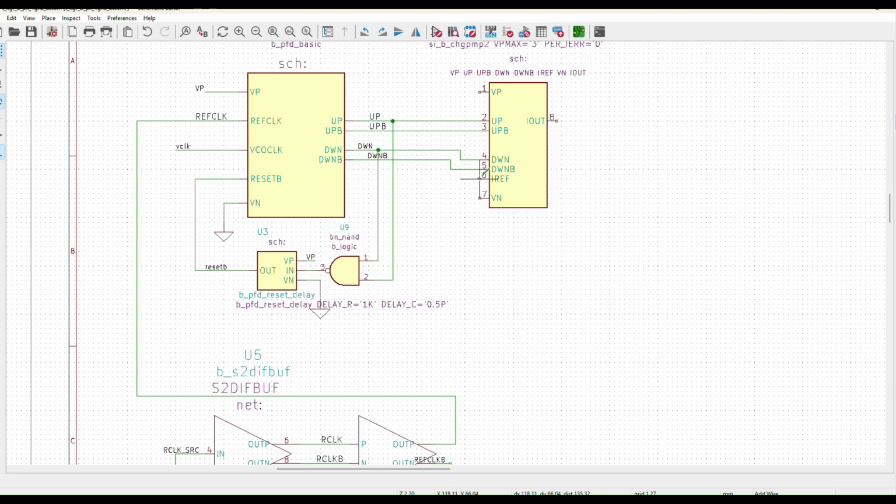Okay, and we're going to have a reference current source, and we need a ground here. VSS is for ground, and oops, I closed that a little too soon. Let me put a net on here and a net on here. So for any symbol, you have to make sure each connection has a net. Otherwise it won't be net listed correctly when you're trying to generate your Spice net list. It's not just KiCad that deals with that, but we used to use, I guess it was Mentor DX Designer, and that had a similar issue.